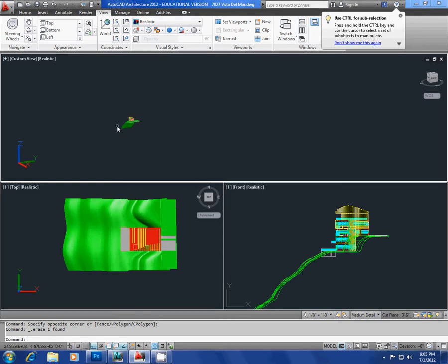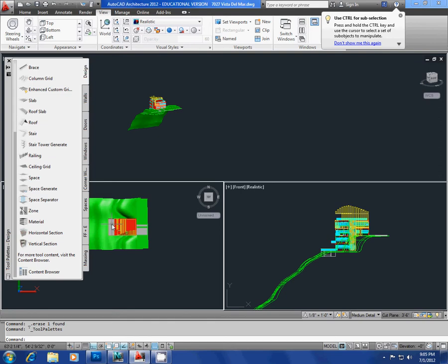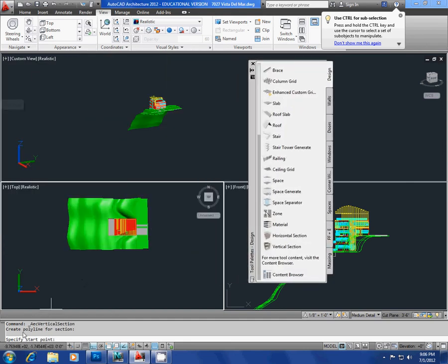So essentially what I do is I'll go to plan view right here, right? And then I'll press Control 3, which is the design palette, and you go down to vertical section, right? Click here, and it asks you your start point. So this is my start point, this is my next point. And then I press enter, and then you can enter the length here. I'm going to put 200 feet. Bam, right? And so you see that there's like this little box right here.